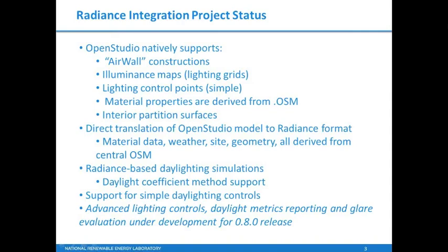So right now, today, OpenStudio supports a direct translation of an OpenStudio model to a fully valid Radiance format. Material data, weather, site, geometry, and schedules, too, which is an important one, are all derived from the OSM. We're leveraging the daylight coefficient method to do the annual daylight simulation, and we have support for what I'm calling simple daylighting controls.